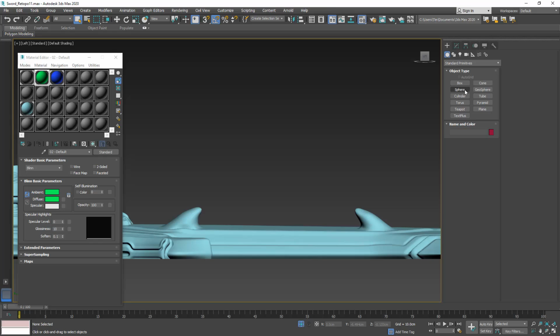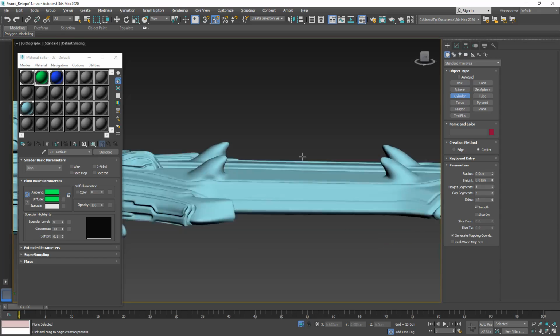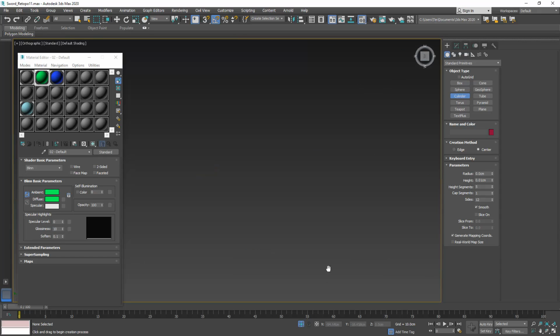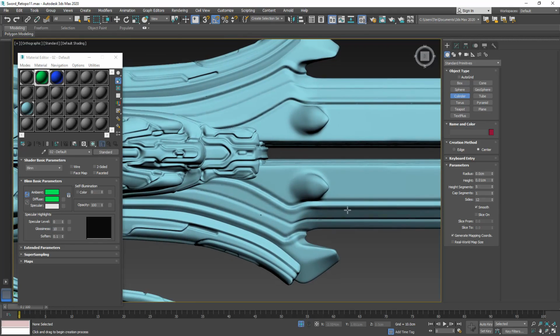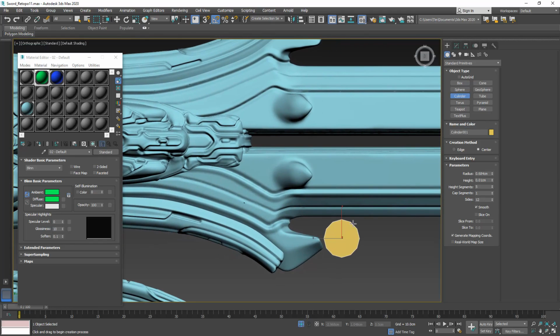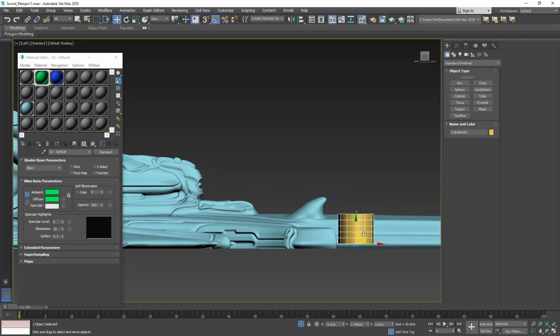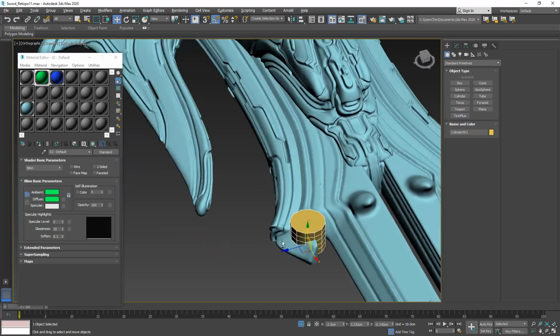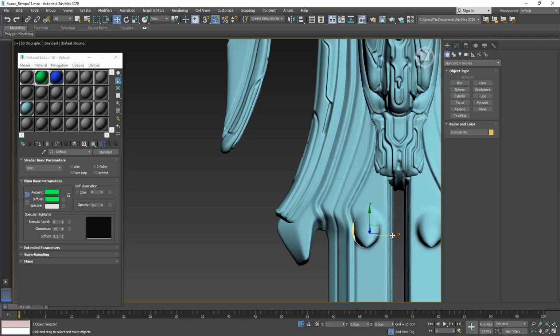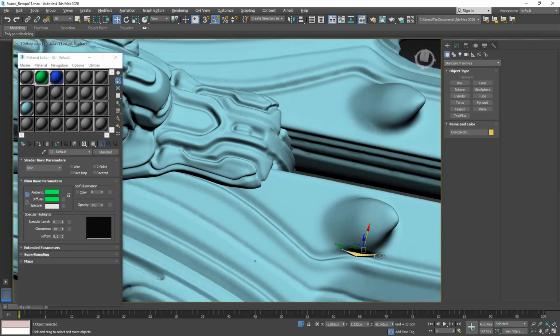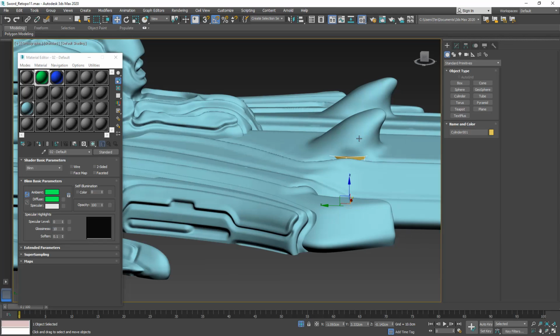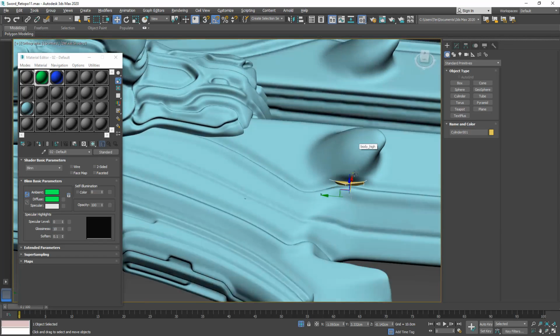And I'm gonna have it in the left orthographic view and select a cylinder here. And actually I want to be in our top view. So let's navigate to our sword here. And I'm gonna have this cylinder here dragged into the canvas. And I'm having 12 sides on it. So now we can go back to the left orthographic view and position it here in the side view. And then drag it over here so that it pretty much fills the bottom of where this knob comes out.